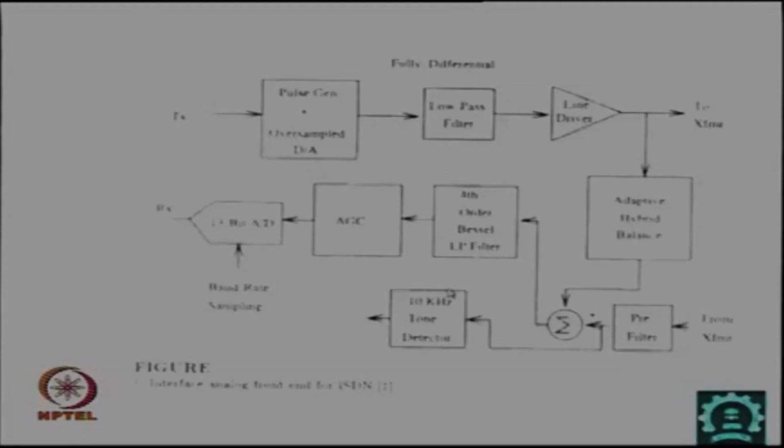Similarly, if you look at a typical system for integrated services for telephones, which has telex, fax, data, everything in one, which is a comparatively higher frequency than normal, you can also see there is an oversampled D to A, a pulse generator, a low pass filter, a line driver which is an amplifier, there is a filter here, a gain control amplifier, and a tone detector. So if you see, once you are in the XFR, you can go digital, but before that the front end everywhere is analog. So our design criterion is that you should be able to interface the digital part and achieve the best performance on the analog or RF part. That is the challenge which everyone faces.